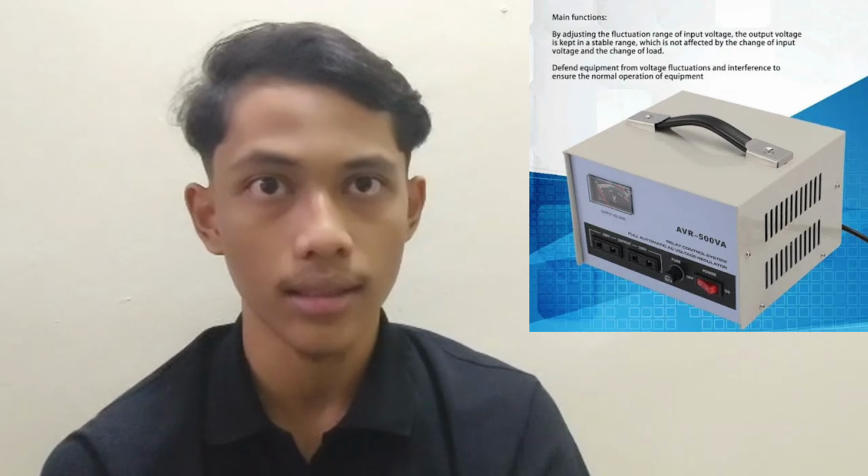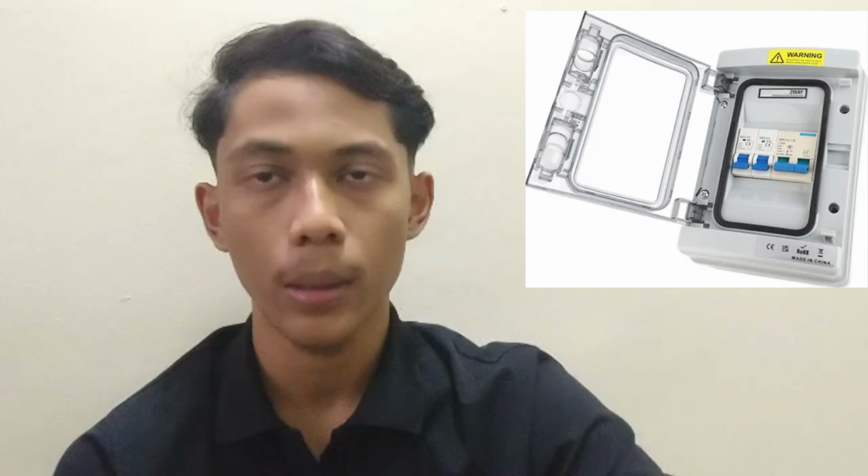The fifth is the inverter and control system. Its main job is to stabilize voltage and frequency for safe use, and this is the part that I researched. The sixth is the distribution system. This part delivers electricity to campus loads such as lights and sockets. This is the distribution system that you can see. Each part is very important and plays a vital role. For example, if the intake is not filtered, leaves or debris may block the turbine. If the penstock leaks, pressure is lost. So design and maintenance are key in this system.